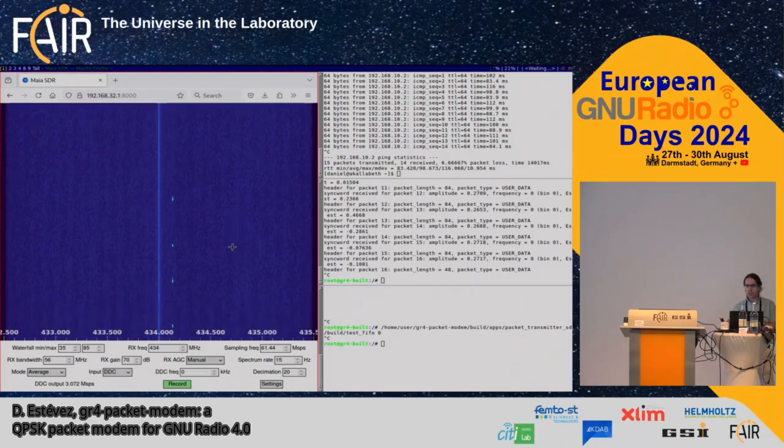The way I'm going to run this is for the receiver, everything is GR4. There is already a SoapySDR block. It can run with the RTL-SDR, 2.4 megasamples a second, 4 samples per symbol, so this is a 600 kilosymbol rate, and this laptop is 13 years old, so this is not a new machine. On a new machine you can run faster symbol rates and nicer things, right?